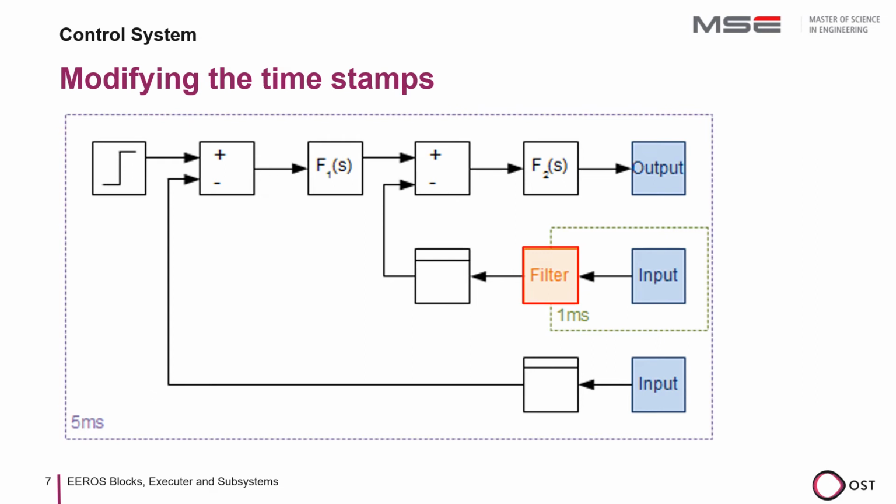If, in the simplest case, only the most recent signal value is used, the timestamp of this value can be copied. However, if a filter is implemented, the signal is delayed by the time constant of the filter. In the case of a transition block from slow to fast, a new individual timestamp has to be calculated for each output value.